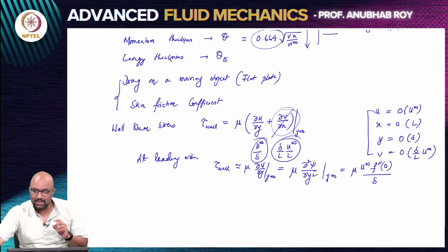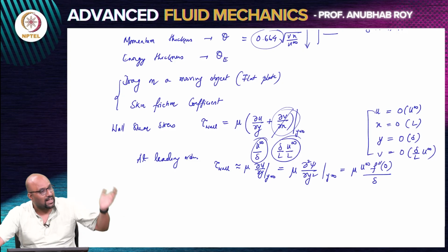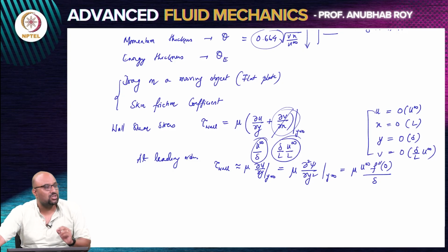See, this is where there is some merit in sometimes thinking of these problems not just purely from a numerical perspective, but also using some approximate techniques. The approximate solution that we obtain, or the asymptotic solution that we obtain for small eta, is not sufficient for you to get the entire picture. But yes, it is indeed sufficient for you to get the wall shear stress. If your goal is to get the wall shear stress, and this is where you have to learn how to use a combination of these tools. You cannot get entire information from a perturbation theory or asymptotic solution.